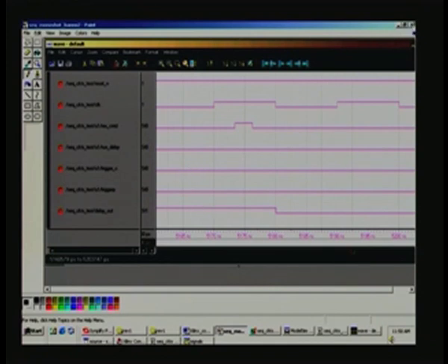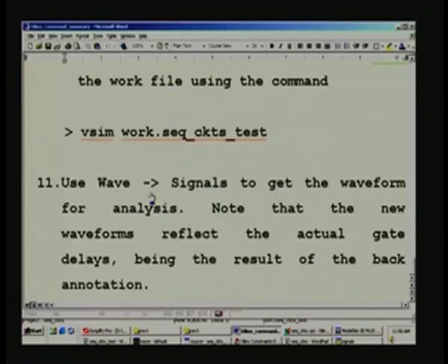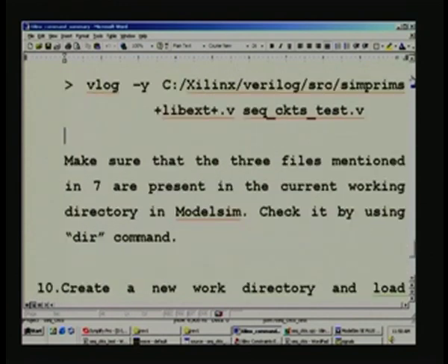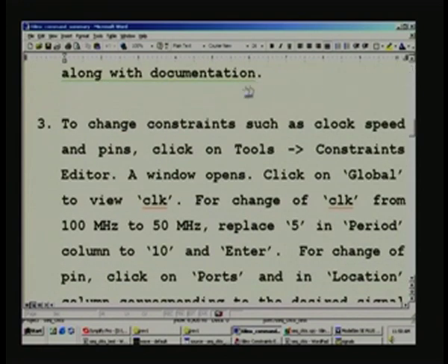So, what we will do next is go back to that Xilinx command summary, that is what we have seen using wave signals. We have seen the back annotated files, and I have forgotten 2 other aspects earlier, that is we have been handling constraints. I mentioned that we can take the constraints straight away from a file and open one .ucf file, and so we will have a little more insight into these constraints, because this is an important thing that we may have to handle quite frequently if you want to make better timing closures.